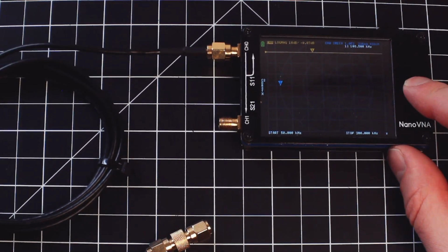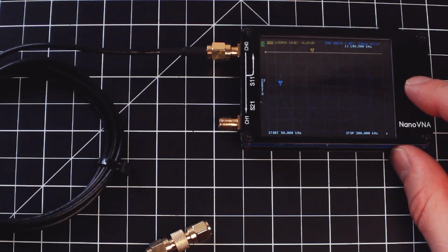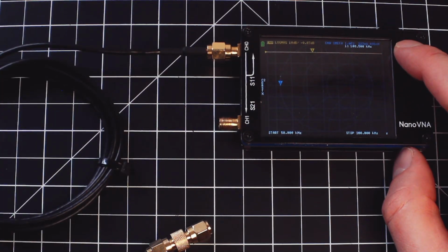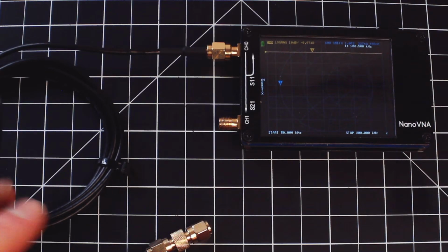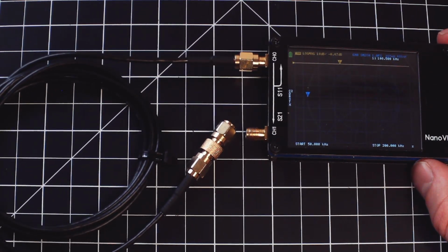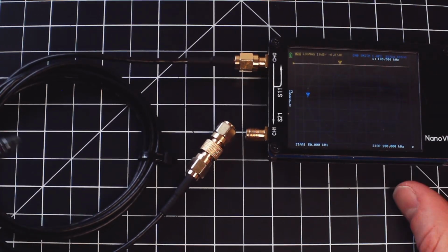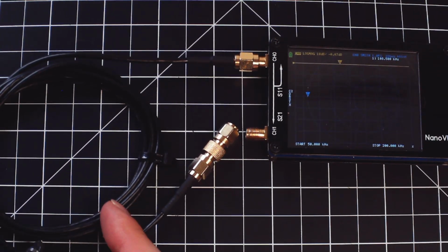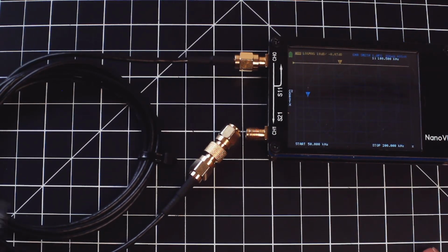And in fact, the NanoVNA is smart enough to recognize that this is now essentially acting like a very big lumped inductance. And so it returns a value of about 487 nanohenries. The problem is this measurement of inductance changes with frequency. Since we are at a very low frequency, the true inductance of this cable is actually higher than it would be if we were operating at, say, 100 megahertz. So this is technically an accurate measurement, but it does not reflect the true inductance of this cable when you operate it at higher frequencies.